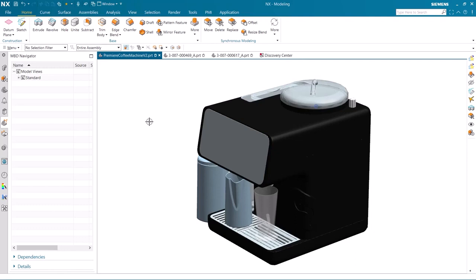In a single part, I added a rule to display the PMI of the holes in the part. We noted that the MBD rule efficiently and smartly selected, added, and grouped associative PMI information to those holes, with hole size and tolerances for each specific hole. The MBD rule utilized a tolerance lookup table that greatly assisted in defining the used tolerances for each hole, and is based on hole size. This removes the need for manually adding tolerances to each hole.